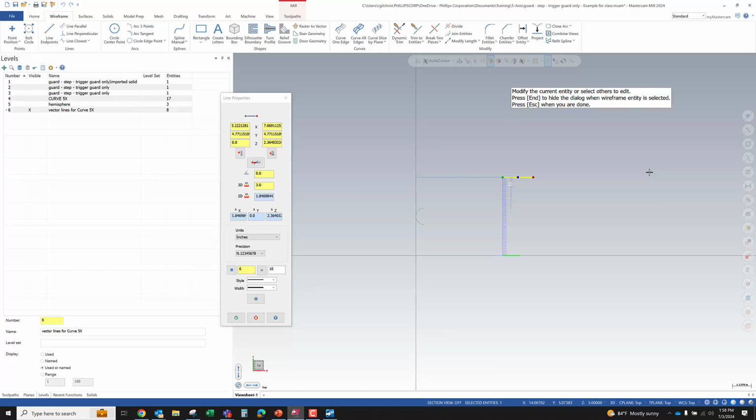So 0 degrees in the top plane is pointing, facing to the right. So doing this with any one angular plane is pretty easy. If you have a compound angle, it's a royal pain. It doesn't really translate if you've got a line that's tilted in multiple dimensions. In that case, I would recommend the transform. But if you're just trying to get a line and adjust the angle, this works pretty sweet.